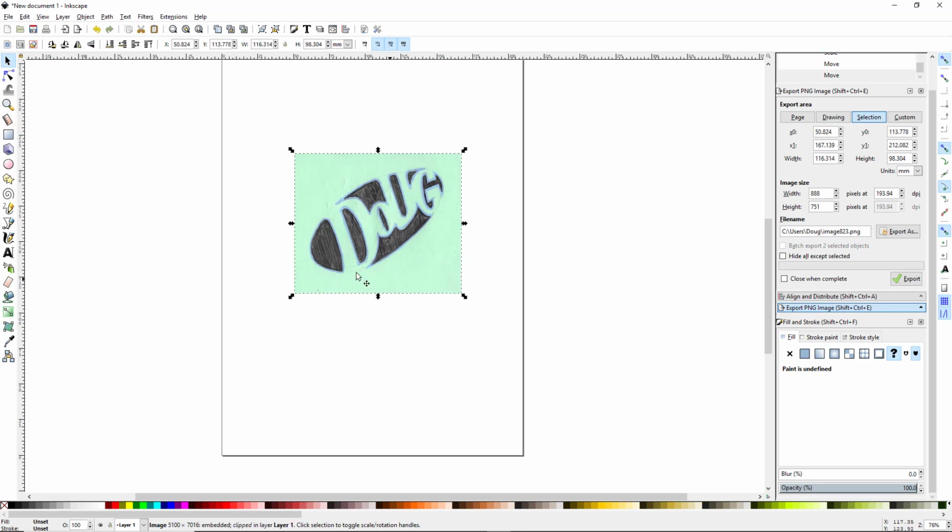And I want to put this sketch on its own separate layer so we're not accidentally messing with it while we're working. And if you can see right here, we're on layer 1. I want to lower the opacity so we can see what we're doing a little bit better. So come over here to our fill and stroke menu, drag the opacity down to about, I would say about 59, 60, whatever, and that's good, so we can still see the lines that we need to work with.